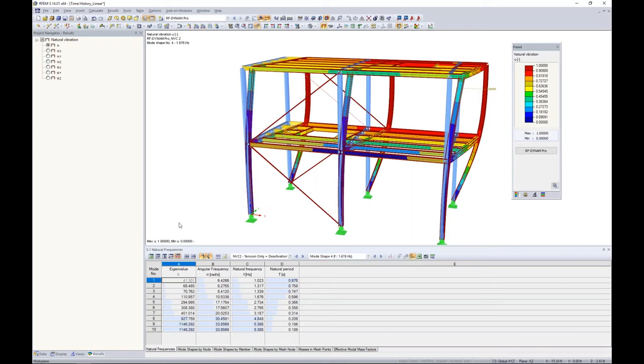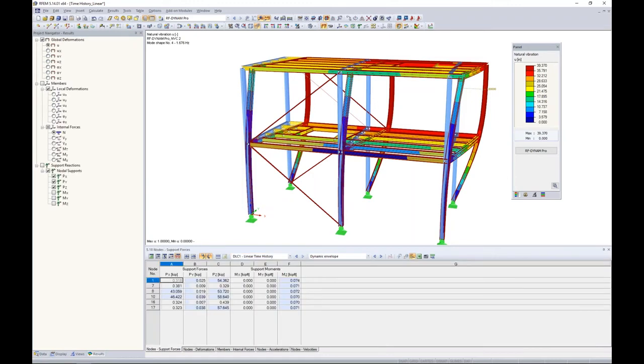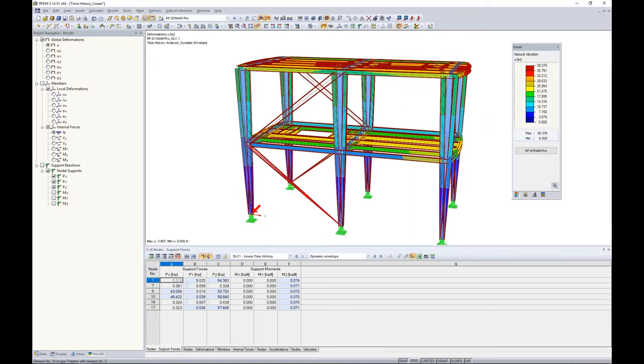So you might think, okay, let's jump back and just do another linear time history analysis, but we can't. If we were to take a look at our dynamic load case 1, linear time history, nothing's changed here. That's because those tension-only members are still being replaced by truss members. We're still going to see resonance because we don't even need a natural vibration case for this particular solver. They're not related whatsoever. So what we do need to do is to move on to a nonlinear time history